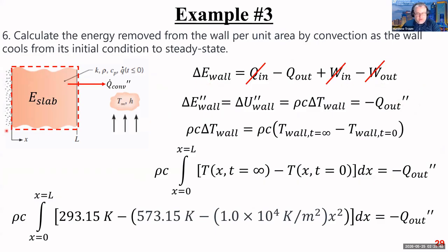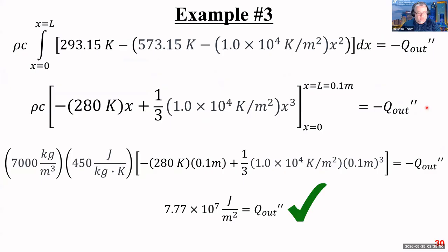So I know that that's tripped people up. Convection is a weird bird, but the negative sign comes from the treatment in the first law of thermodynamics, not from putting a cold temperature first and a hot temperature second in that convection equation. Okay, this checks with what the book says.